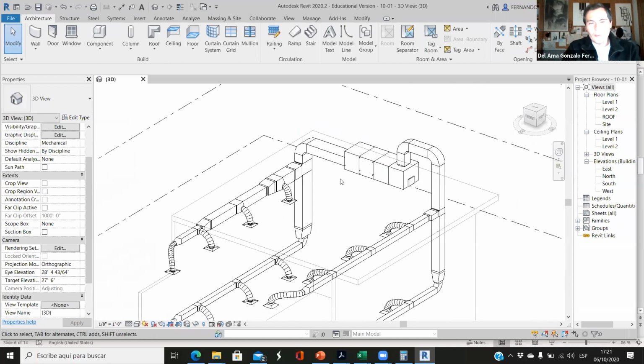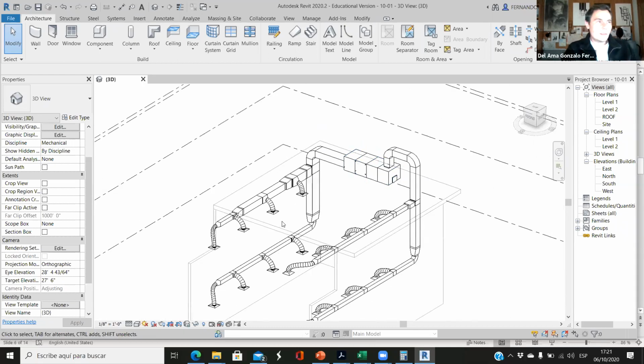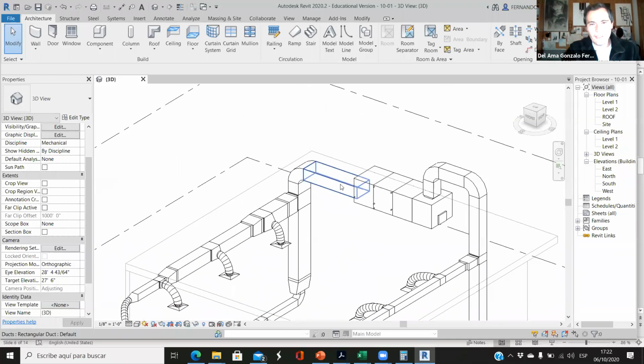It's about experience. When you have done this many times, you see this CFM and this duct area, kind of, and you don't have to think about it. But when we are not experts, we either do it by hand, which takes forever and is a nightmare, or we just make a rough calculation with the total CFM, and then find the maximum area. So the maximum area would be this.